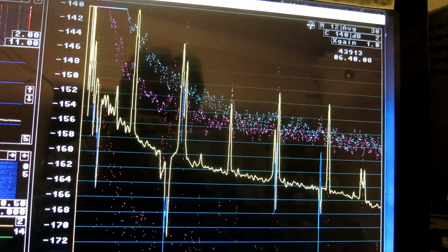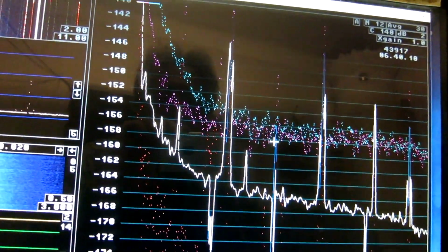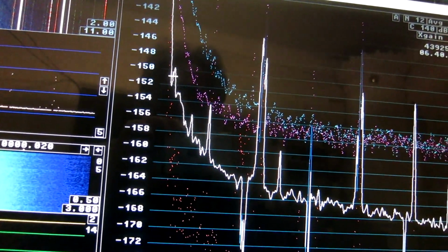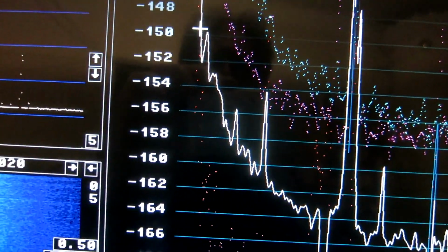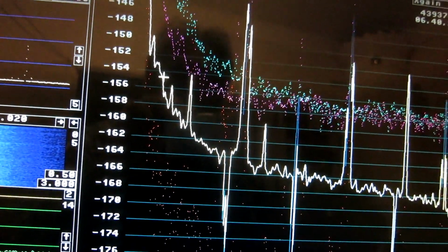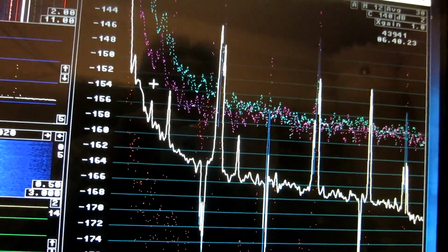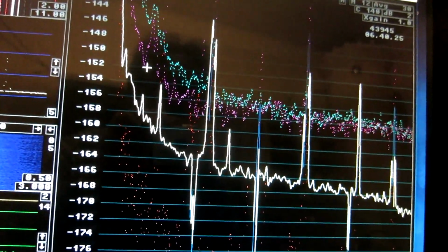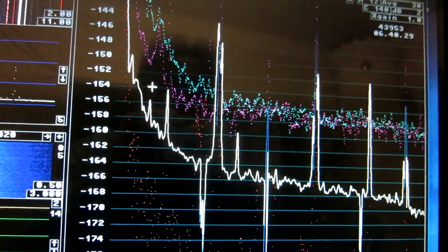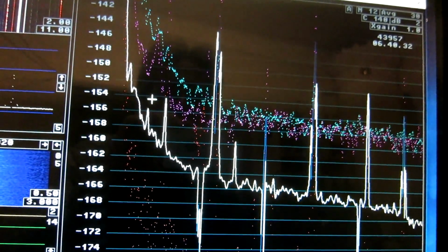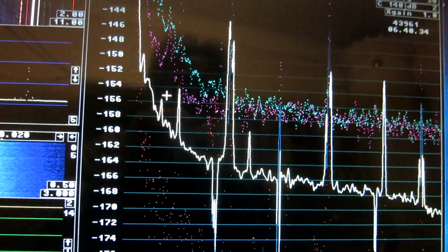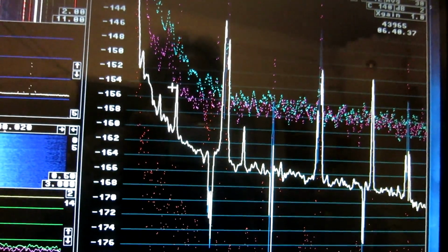And look at the AM noise. And amplitude noise, I can go a little bit closer here. And it is very low compared to what I have seen before. And that's interesting to me because it opens possibilities to investigate amplifiers by use of this, investigating amplitude noise of amplifiers.